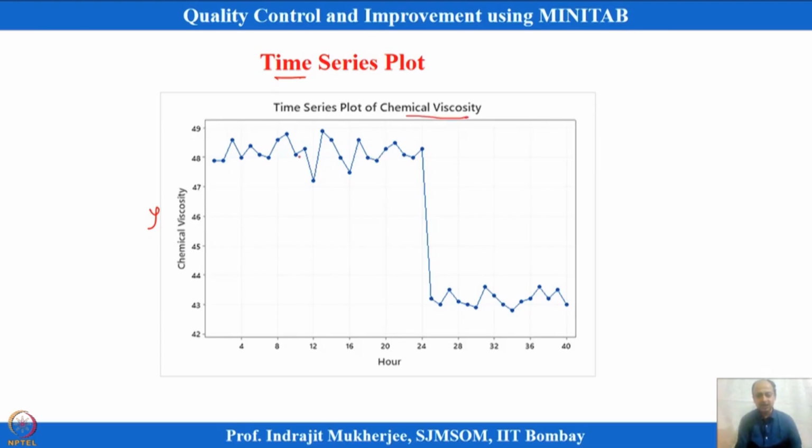What you can see over here is that the average or accuracy of the process is more or less over here, but suddenly it has dropped at the 24th observation and the average has moved over here. So, the centering of the CTQ values has drastically drifted from one location to the other with respect to time. So, I can monitor with respect to time and plot that.